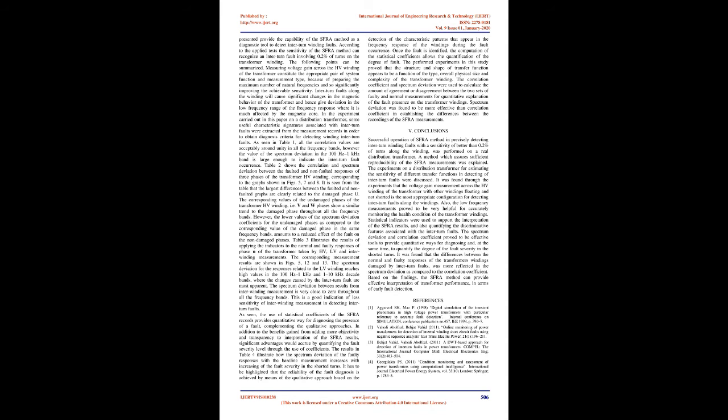However, there is not a visible fault indication in the low frequency range of the transfer function, which looks very different to the HV and LV winding measurements. The low frequency deviation in the winding response as a result of interturn fault is governed by the interaction between core and windings, while the interwinding measurement is made with almost no reference to the core effects at lower frequencies.